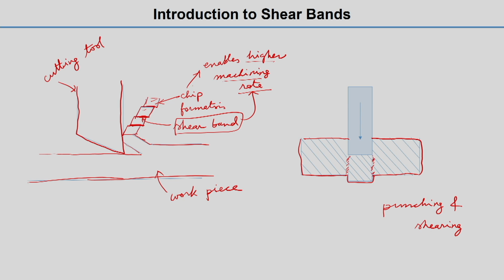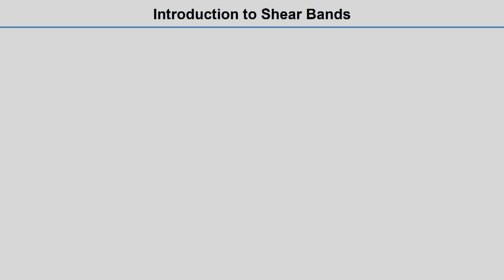in this line. So there are small shear bands here. These shear bands will help smooth cut. So that means the shear bands are important. They are sometimes desired, especially for manufacturing processes, but otherwise, if you see for armor applications, shear bands may not be desired in all cases. We have already discussed the basics of shear band even earlier.